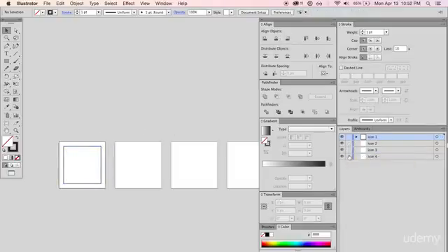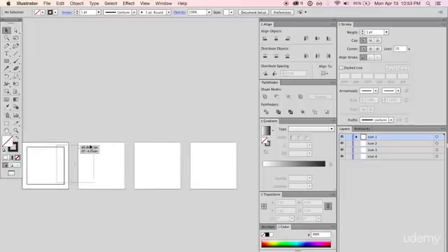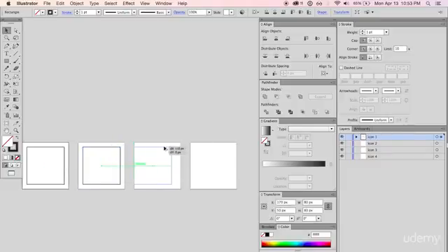And next what I'm going to do is unlock these layers because I'm going to put my rectangle in them. So if we hold Option while clicking on the square itself, we can actually drag and duplicate. And while holding Shift, we can make sure that it locks into that straight line, so it's not going to go up. So let's go ahead and lock that in here. We're going to duplicate it again, and one last time, just so we have a good baseline to start off with.